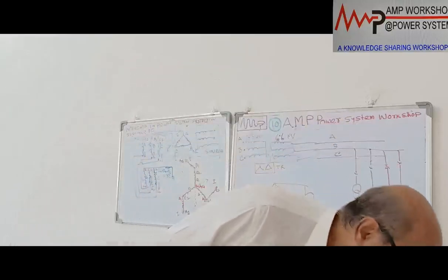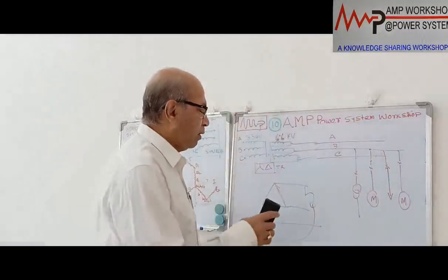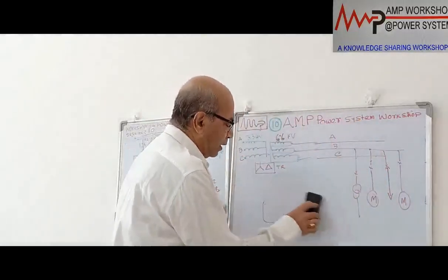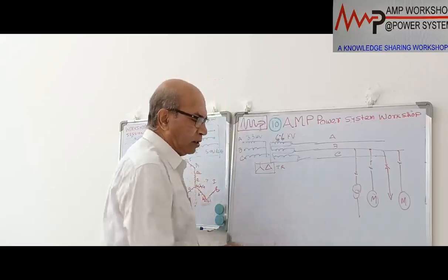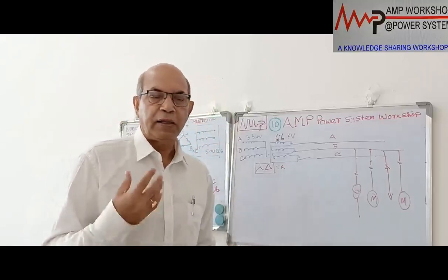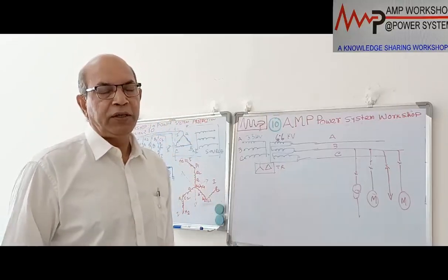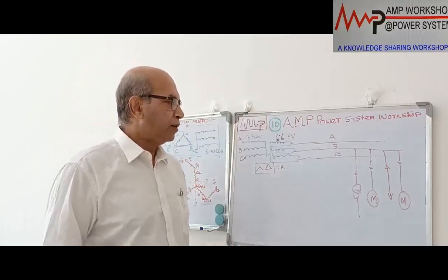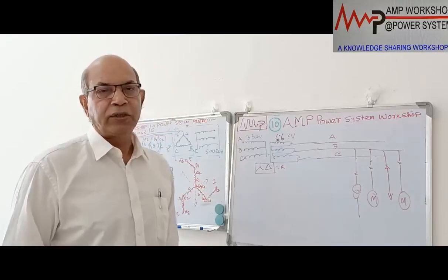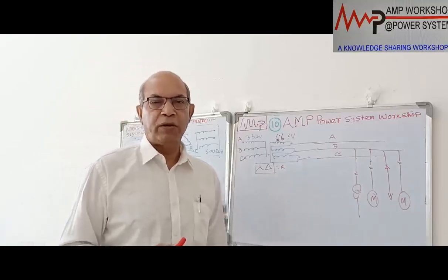So just to avoid this, sometimes the utility company feels that this delta connected system should be grounded by an earthing transformer. I did one job about 25 or 30 years back on the same kind of delta connected system, at Bandel Thermal Power Station in West Bengal, India.